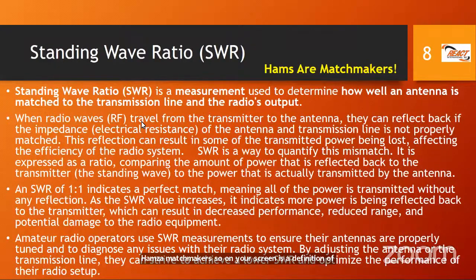It gives a lot of detail. So of course, this is not all necessarily on your exam, but I'll leave it to the participants. You get this slide deck so you can read this through. But we just mentioned that standing wave ratio, abbreviated as SWR, it's a measurement and it tells us how well our antenna, remember we are as hams looking to use our transceiver or transmitter to transmit into an antenna. So it is saying how well that antenna is matched to the radio's output as well as the transmission line that we use. So we'll get a little more into that using a diagram, but the rest of it here is for your reading pleasure.